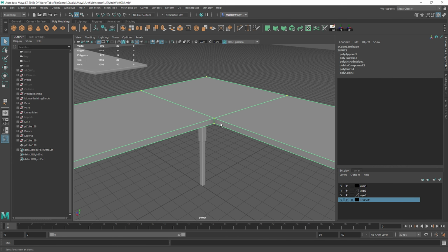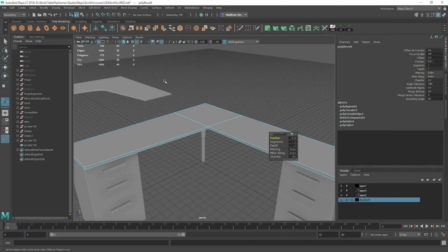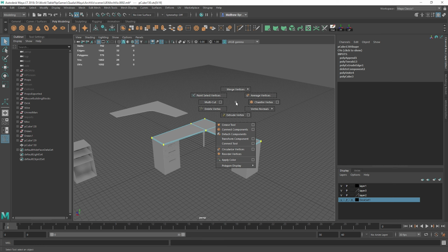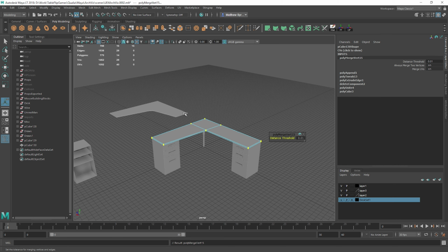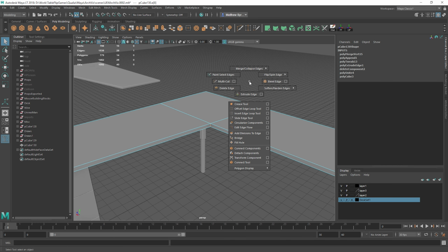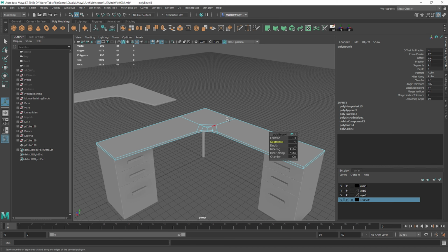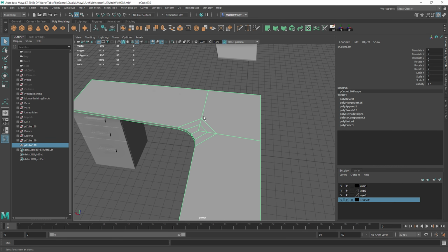And then what I did was I selected this edge here and beveled it, but it won't work because it's still set to 20 verts, which is not right. So if I grab all the vertices and merge the verts, using Shift and right mouse button, it's now 16, and it will let me do a bevel. So bevel's quite good at telling you if you've got a problem. I'm going to make that 0.3 and change this to 4. So I'll get that.